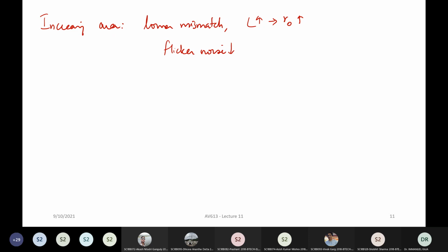But for things like current mirrors, you cannot do chopping, and you cannot do switched capacitor based offset cancellation techniques. The only thing you can do is increase your area such that your sigma I out comes within tolerable values. Given the sigma I out, you can also calculate it in terms of percentage.